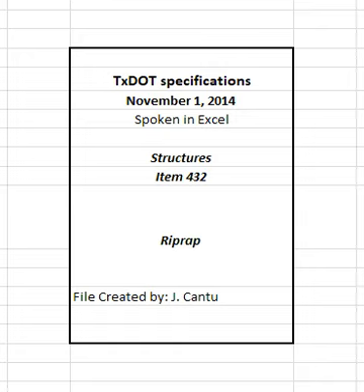If required, provide bedding stone that, in place, meets the gradation requirements shown in Table 3 or as otherwise shown on the plans. Determine the size distribution in Table 3 in accordance with ASTM D6913. Table 3. Protection Riprap bedding material gradation requirements. Sieve size, square mesh, and percent by weight passing.